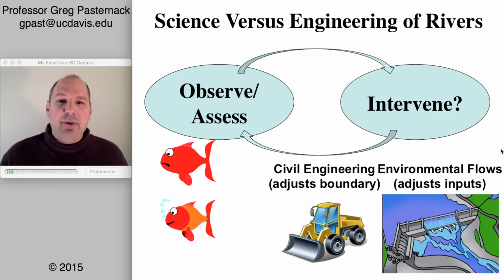Now I'll give you a simple example. Let's say you have a road and they just paved the road right across a stream, just bulldozed, paved. And now, the river, maybe it's in an arid setting anyway, so there's sometimes no flow. When there is, it just floods over the road. Or maybe they put in a culvert with a step in it or something like that. Basically something that is a barrier to flow, sediment, and of course prevents organisms from moving upstream or downstream.